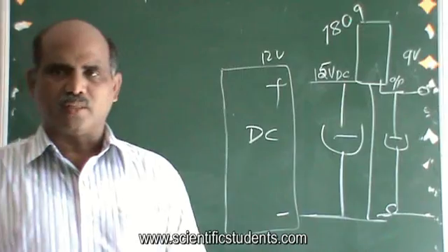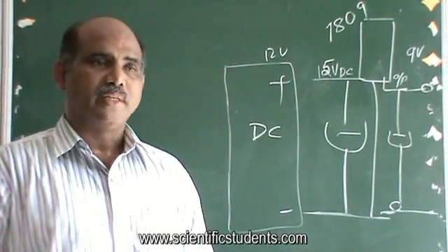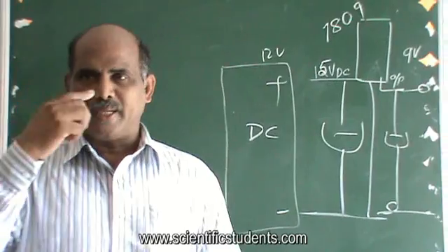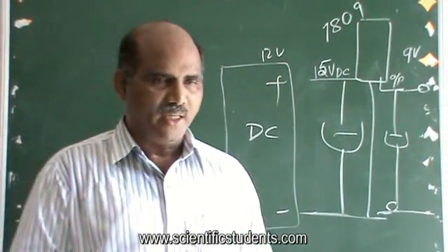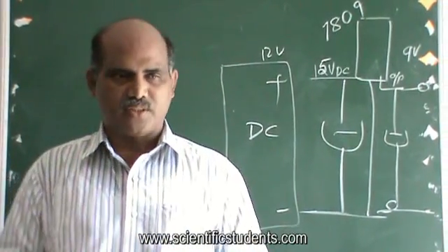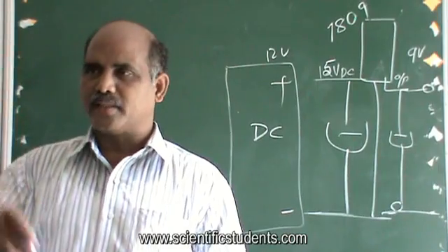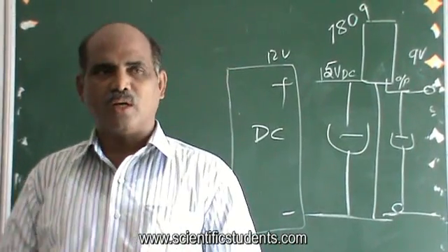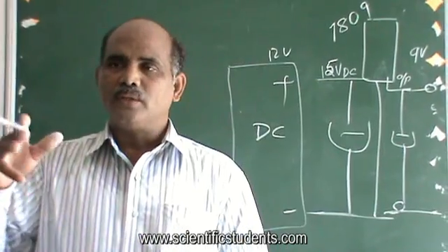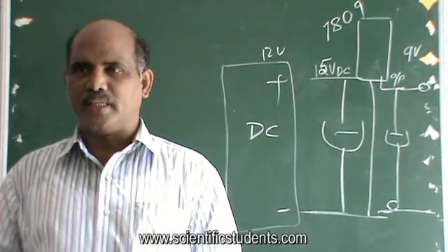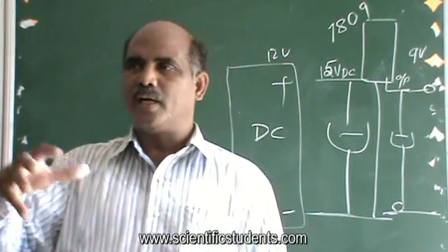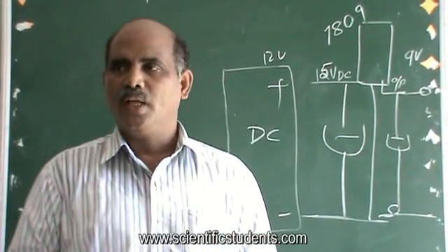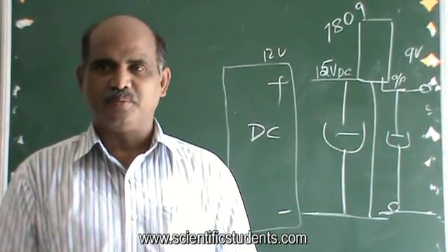And AC to DC we talked about. Also we can talk about DC to DC. They are called DC-DC converters. Very important, because when you want to work with solar energy, you need to know about DC to DC conversion. Solar energy comes from photovoltaic solar plates, and when light rays fall on the solar plate, the electrical output you get is DC. That DC you again control into DC to charge the batteries. So intermediately you use a circuit called solar charge control units, CCUs. They are nothing but DC to DC converters.